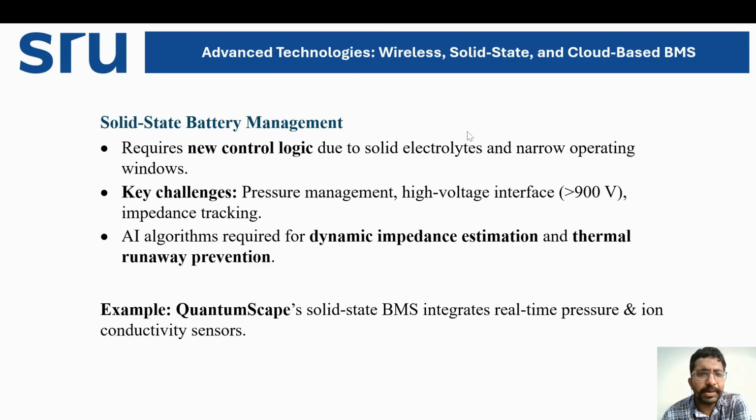So, solid state battery management. Advanced technologies. Already we have seen what solid state battery management is. It requires new control logic based upon the solid state. With solid electrolytes, narrow operating windows will be there. Key challenges will be pressure management and high voltage interference, greater than 900 volts, because here liquid electrolyte is not available.